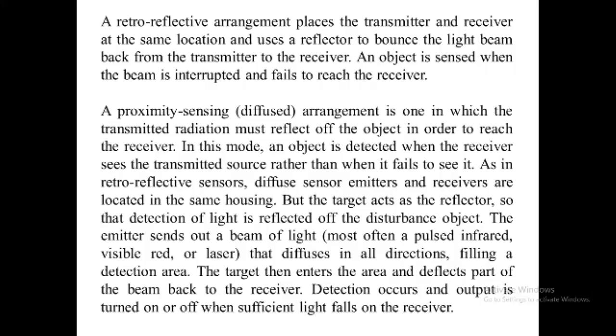In addition, polarized retroreflective sensing features a polarized optical block which reduces the response to hotspot glare from the shiny surface of the detected object.